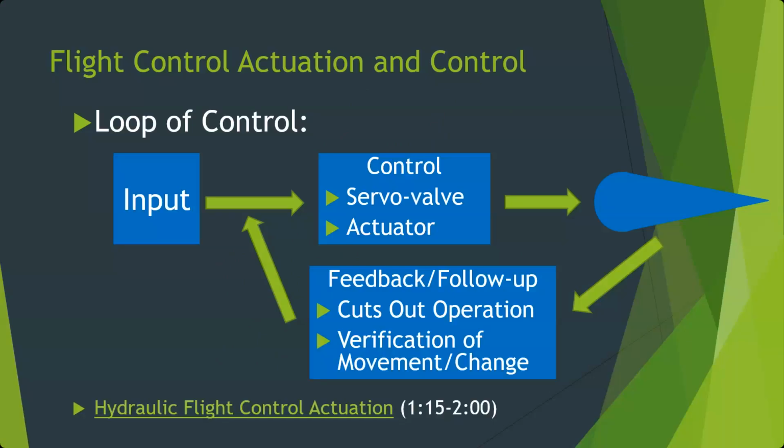It's also used by things like the autopilot, so the autopilot can see it moving. And then it also feeds into things like the flight data recorder, the black box, so to speak, that records all the aircraft parameters. That box will be recording the actual physical movements of the yoke. It'll also be recording the movement of the flight control so they can be compared if there's an accident, to tell whether it was the crew doing the wrong motions with the yoke or the rudder pedals, or whether the flight control itself failed to move.